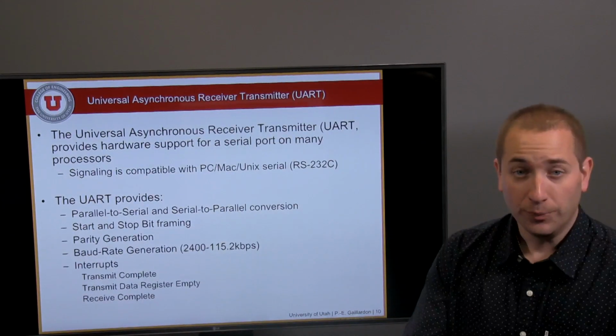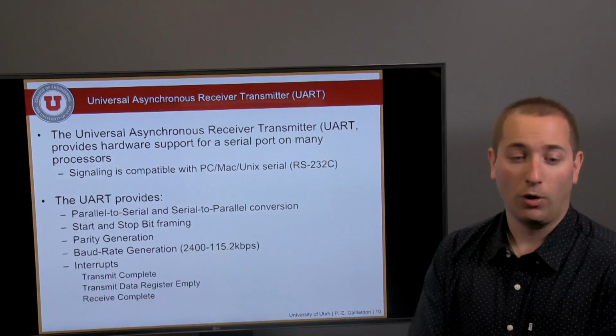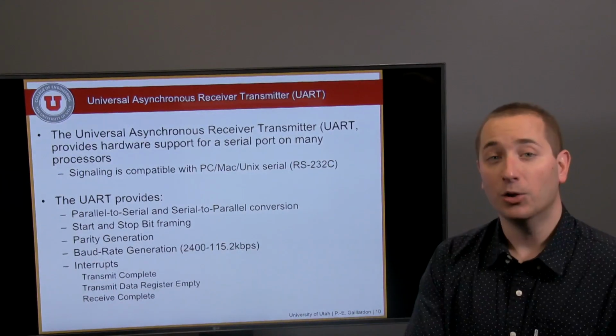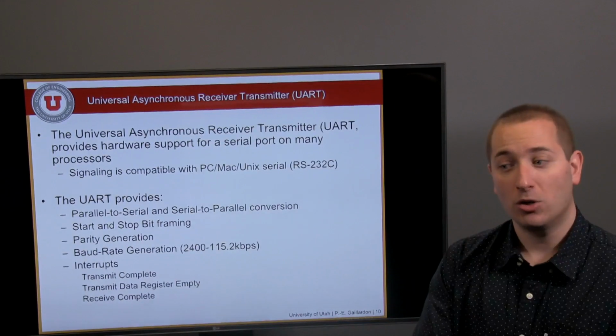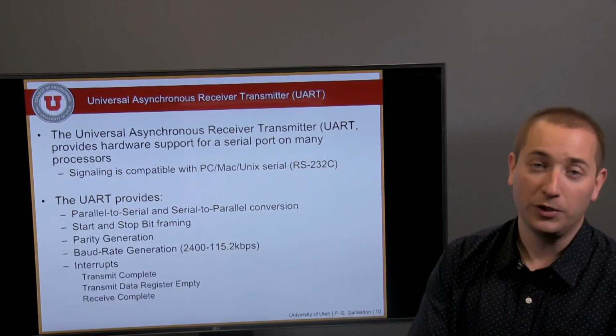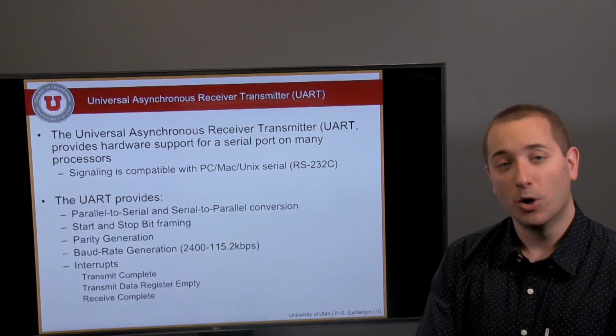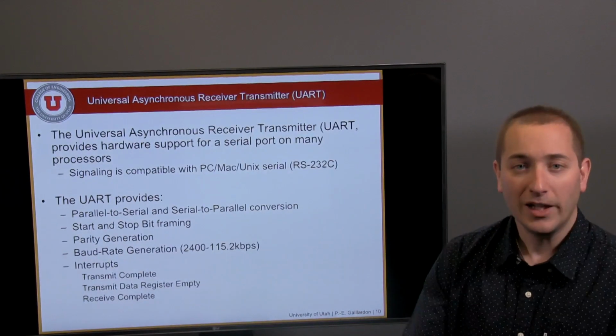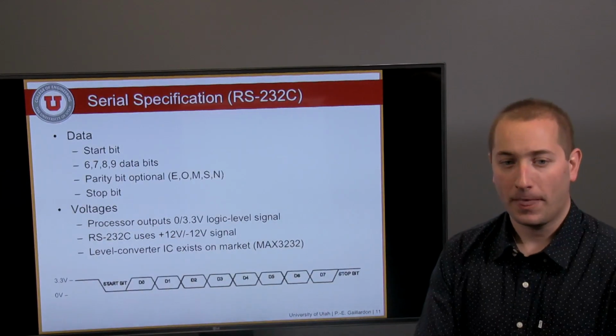On the microcontroller, this UART module supports several interrupts as well, to tell you when you receive some information or when you have been able to transfer successfully some information and you need to feed the module even more. Let's review what the protocol looks like.